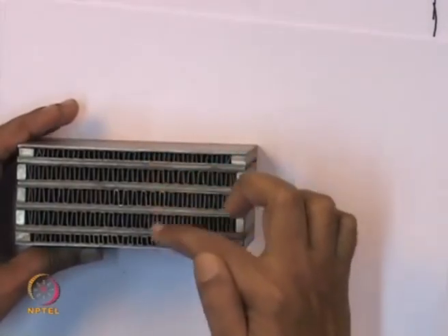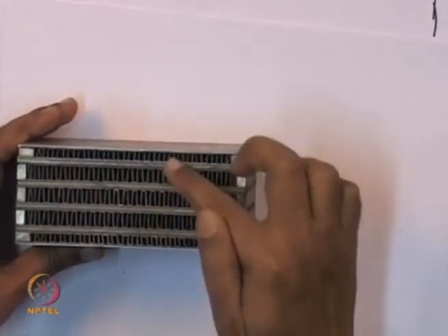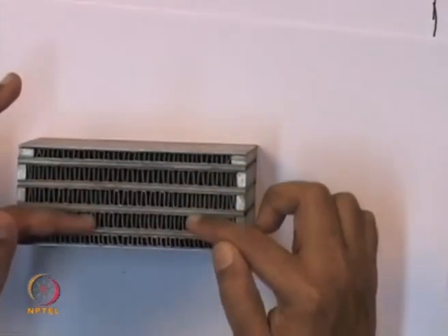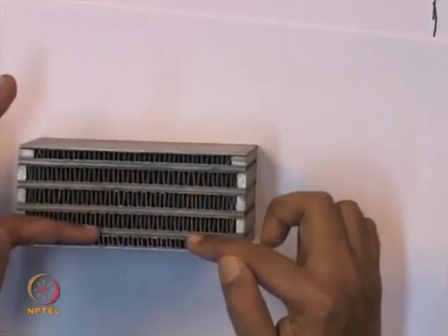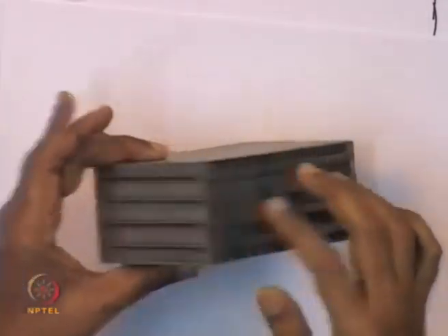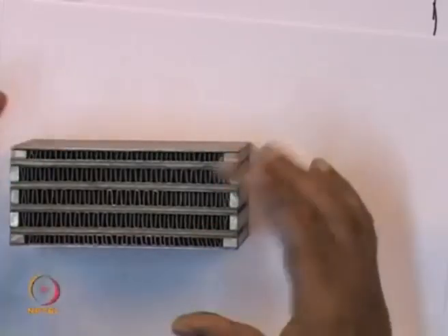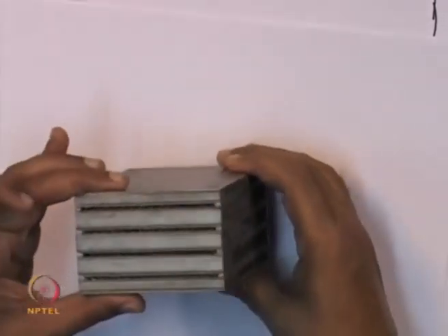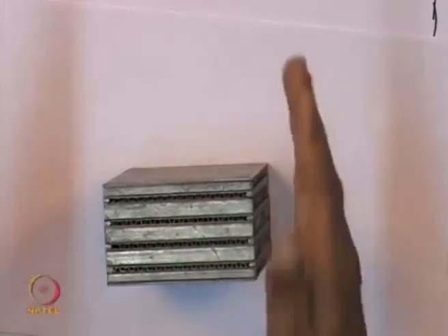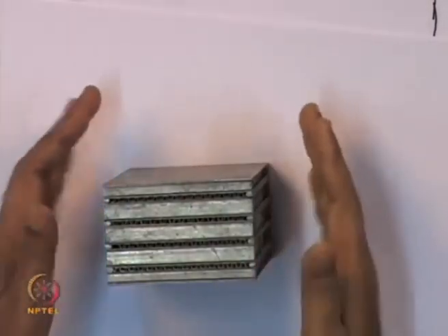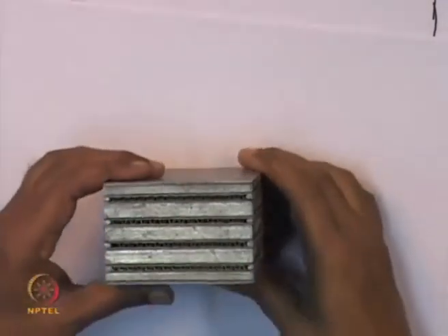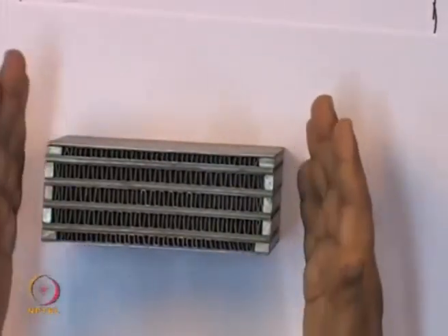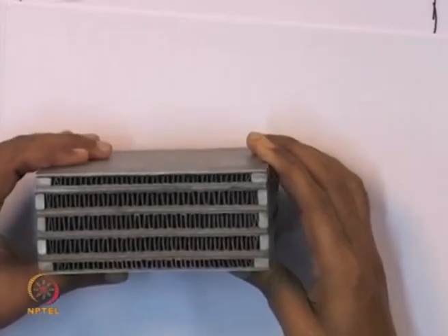Now, there are different fluids that could go in these directions also. So, we can have one fluid going through these top two layers, and the other fluid going through the bottom three layers also. Similar thing can happen over here. So, you can have multiple fluids exchanging heat in a plate fin heat exchanger, and one can see how compact it is. And you can imagine such units made in a length of 1 meter or something like that with 10 layers or so, then you will have a tremendous heat transfer area available in a given unit volume, and this is what we call an aluminum brazed plate fin heat exchanger.